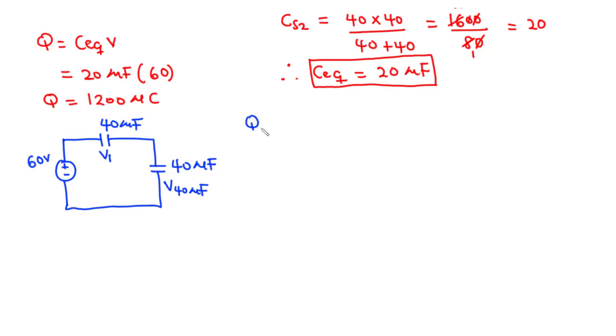So in that regard, we can say that since we know that they are in series, the total charge Q is said to be C1 V1, and that is also equal to, in this case, we can call this 40 microfarads times the voltage across 40 microfarads. So don't be confused. This is for that, and then that is also for that.